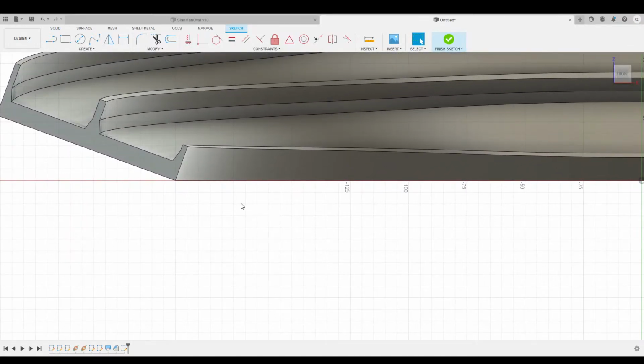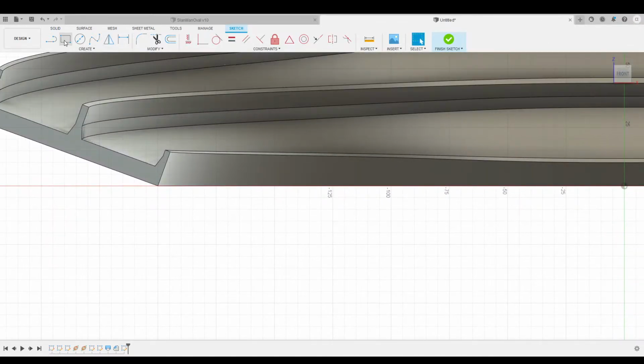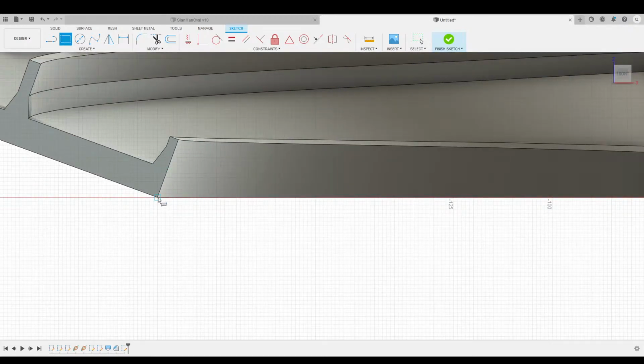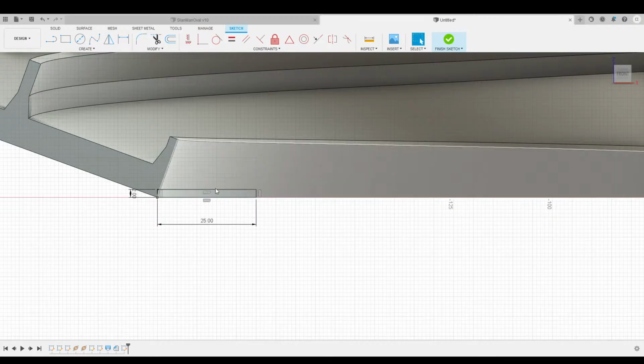And we're going to come in here. And this stuff doesn't usually get messed with after you create it. So we're actually going to create a box. We're going to make sure we got our little square down here. We're going to like that. And usually I think we do 25 and 2. Okay, and let's hit enter. So this is a fully constrained box that's just kind of drawn right here. And we're going to finish that sketch.